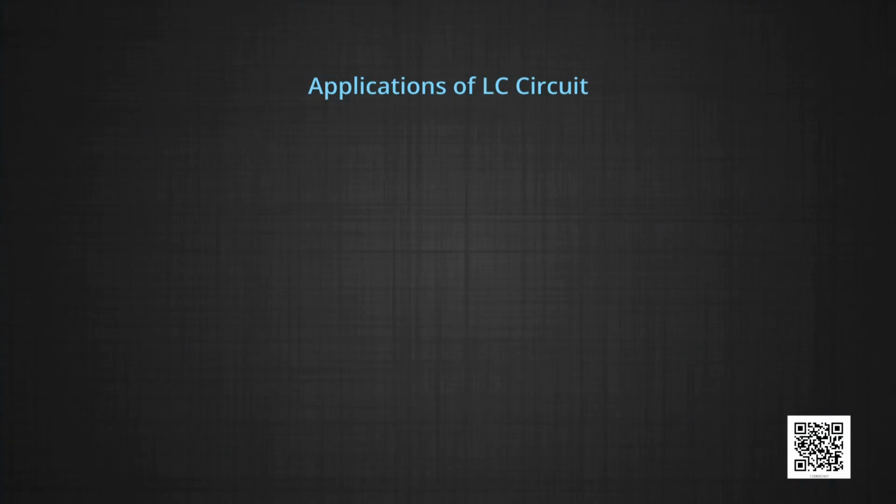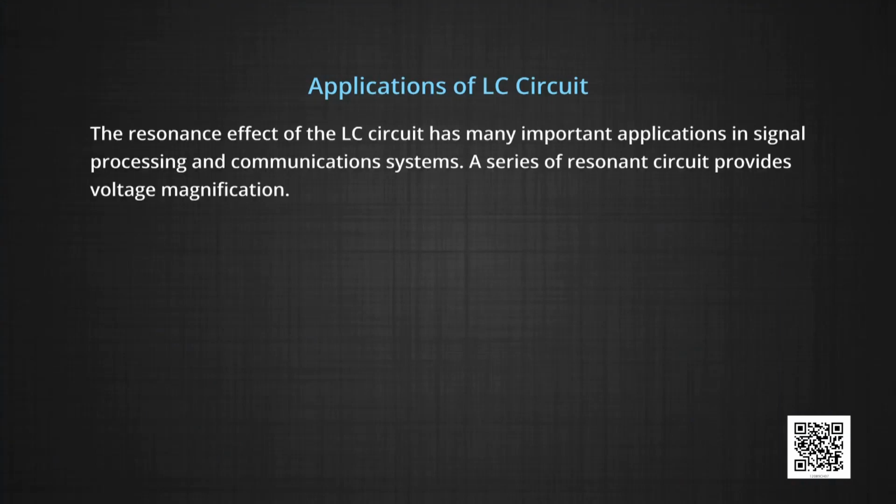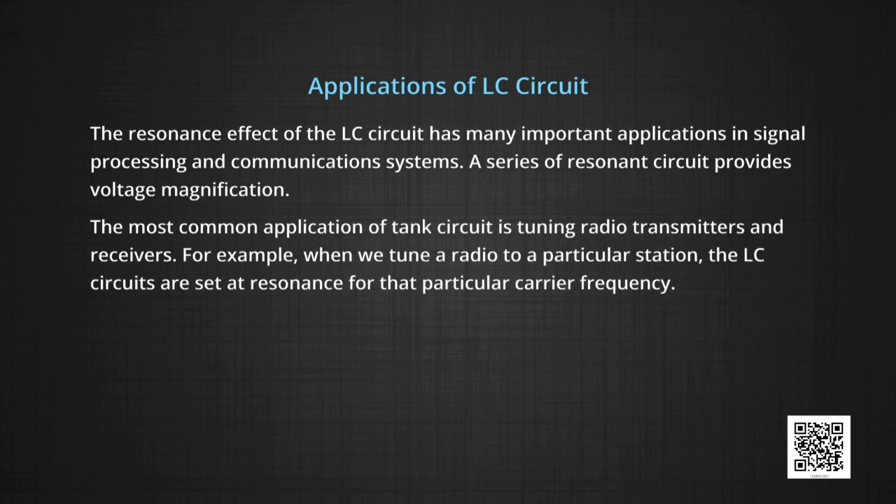So, here we can talk also about the applications of LC circuits. As the resonance effect of the LC circuit has many important applications in signal processing and communication systems, a series resonant circuit provides voltage magnification. The most common application of the tank circuit is tuning radio transmitters and receivers.